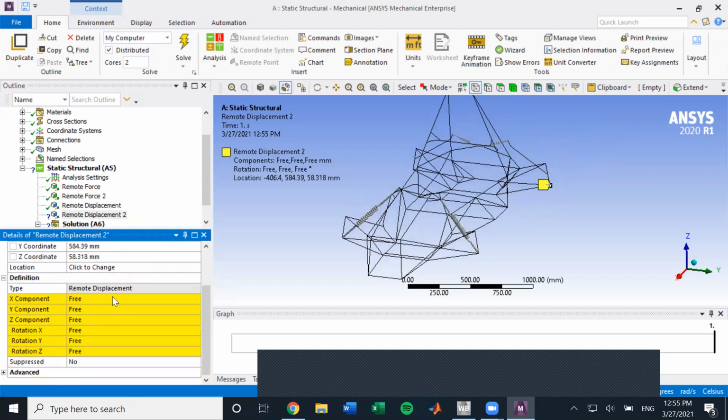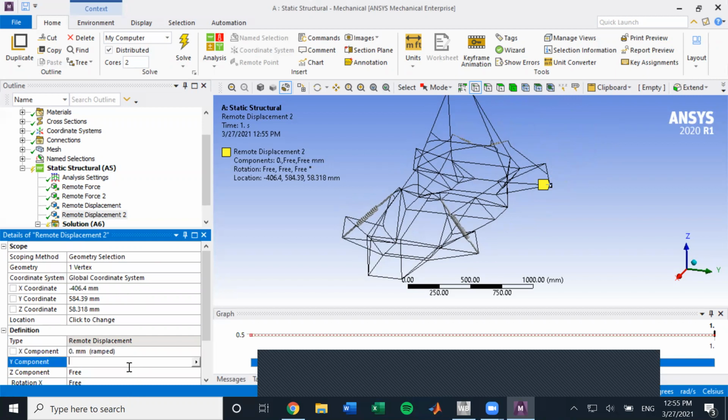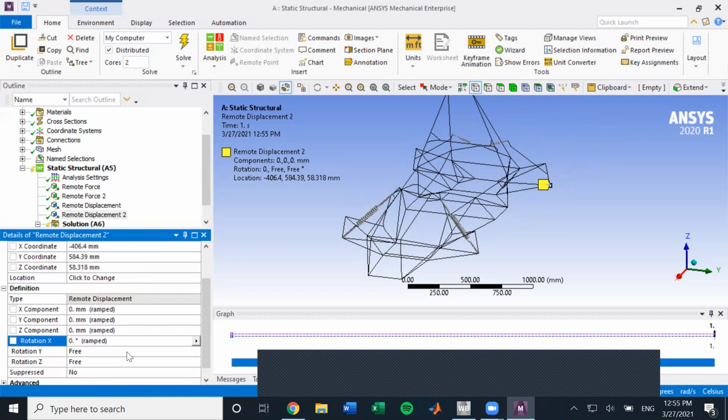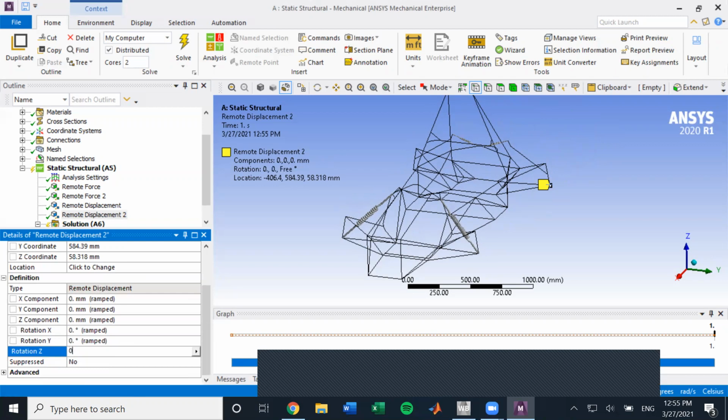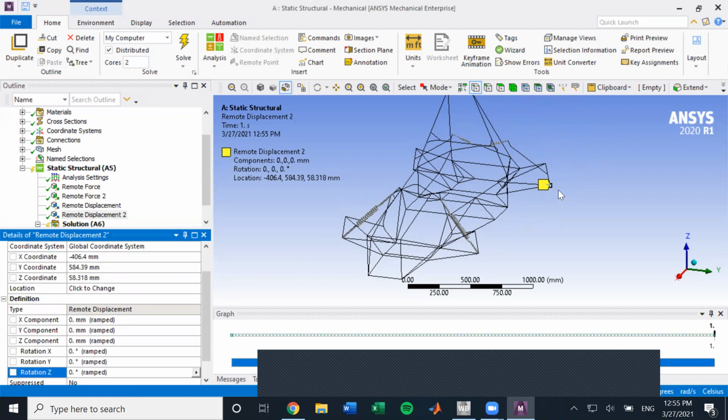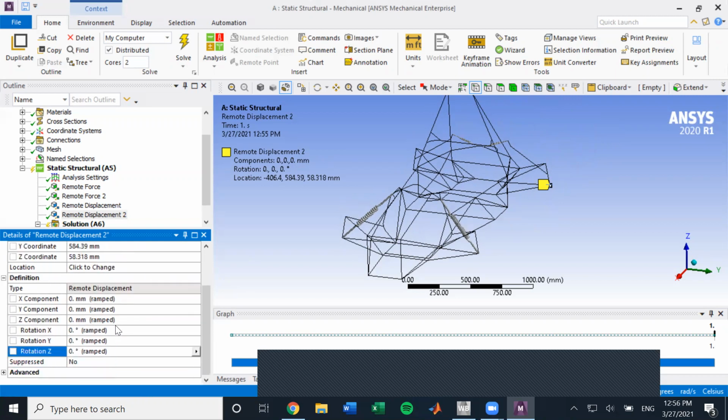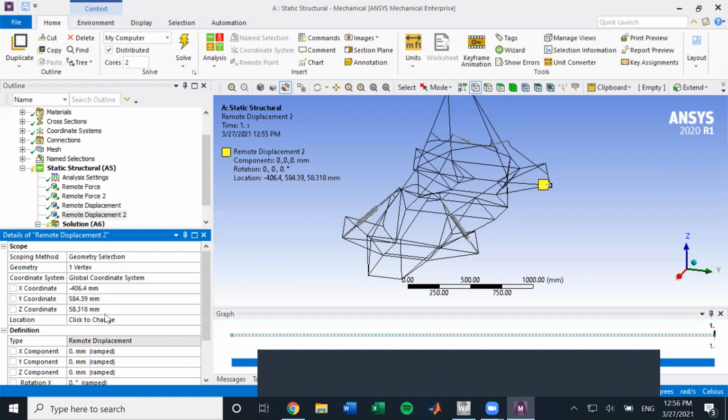So at this point, we want to have no XYZ translation and also no rotation. If you recall from the paper that we were referencing, this point is completely fixed as the boundary condition, and the point at which we want 0 translation and rotation about pretty much any point on the vehicle. Right now, the point is just right there, which doesn't matter too much in this case. It will matter when we get to the rockers.